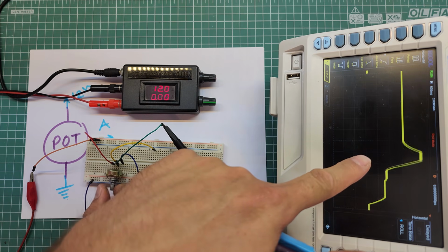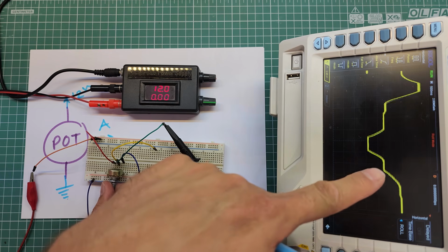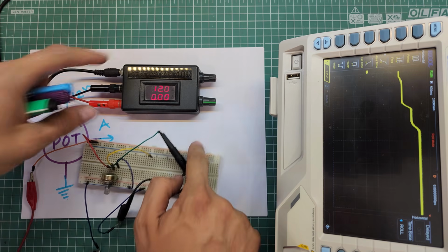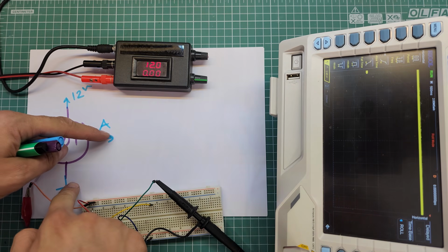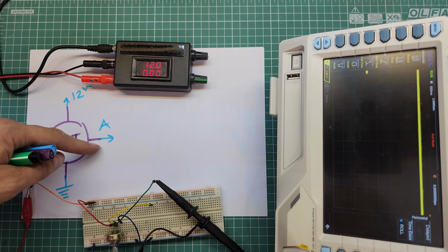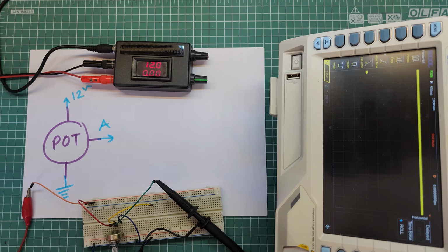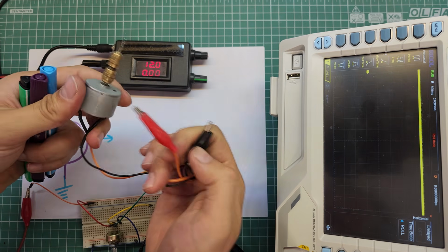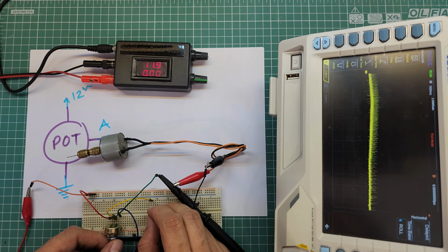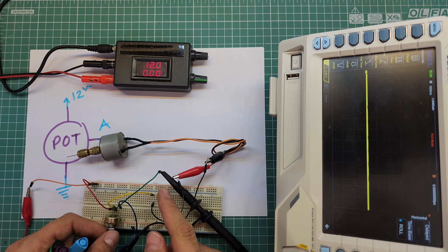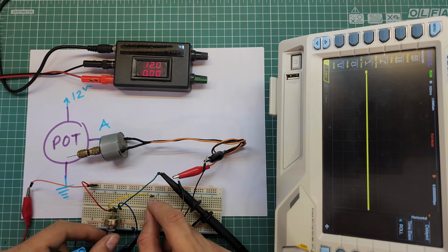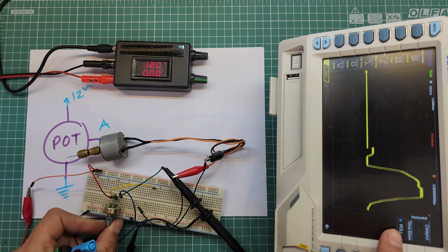But this variable voltage is so weak and useless because it can't deliver current. For example, if I connect the DC motor to this point, I mean point A and ground, hoping to control its speed, voltage on point A will drop to 0 and can't run the motor. For example, this motor. This is what I call a weak signal or weak voltage. There is no problem with voltage range. It is between 0 and 12 volt.